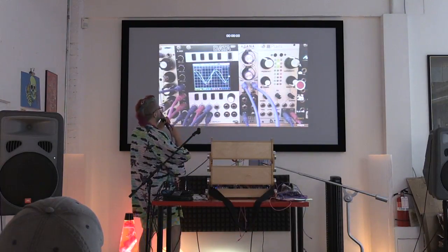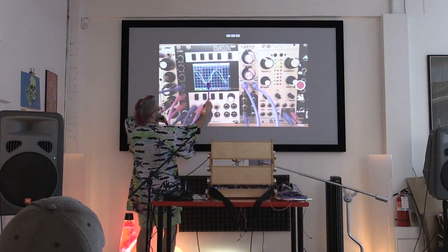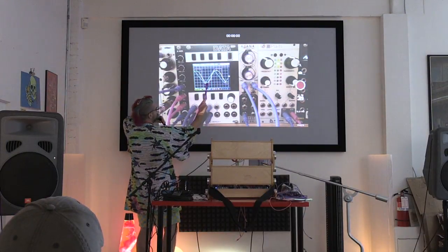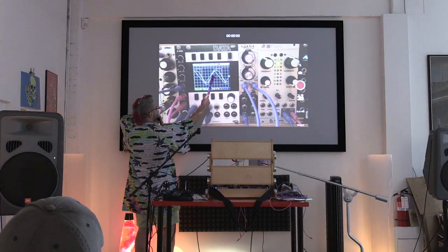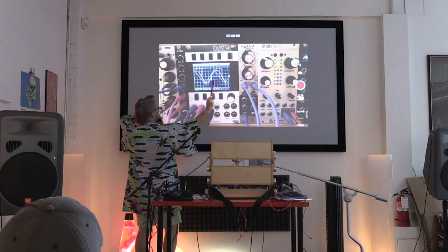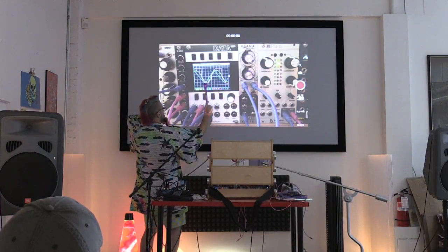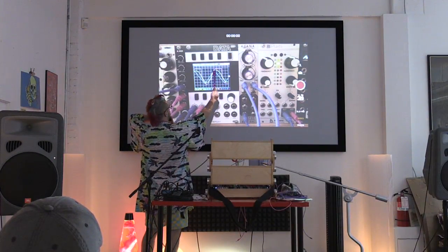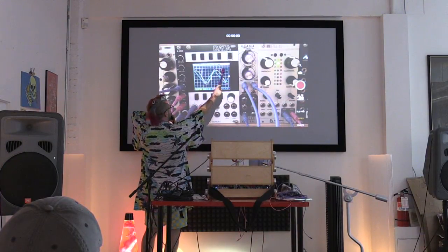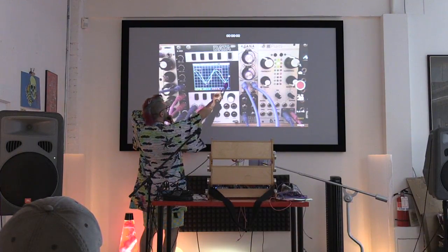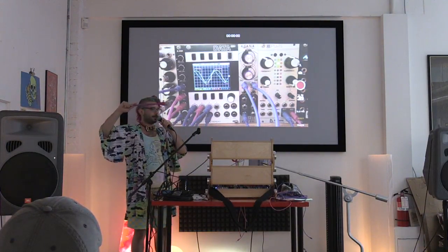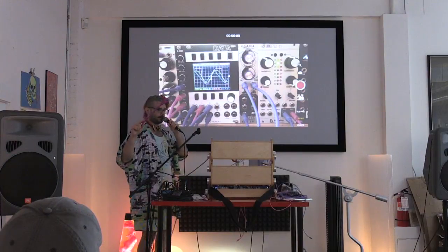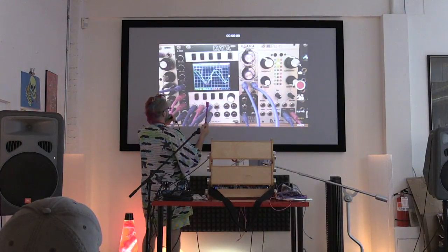Okay, perfect. So you can see right here, we have our original signal going through. And then right here, it's deciding to make a little almost incision into our wave and hold it for whatever period of time it decides to do. Then here, we're back to our original signal. Here, we're holding again until it jumps back to the original signal down here. So a sample and hold will just give you those stair steps. It never lets the original signal through if it's designed correctly.